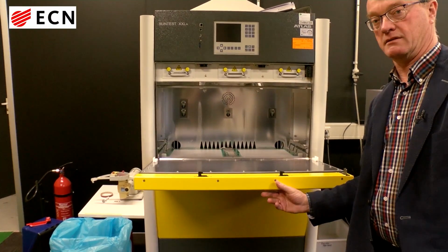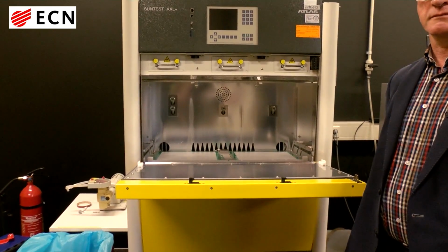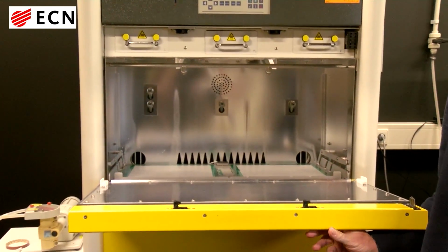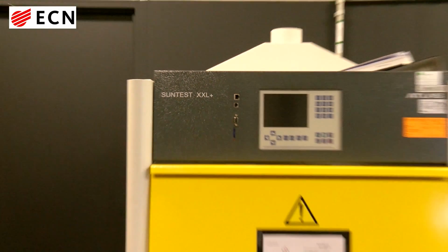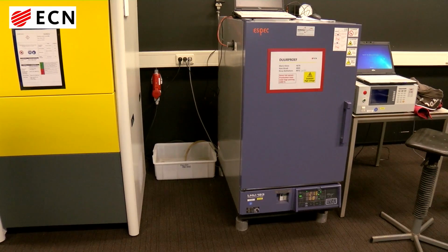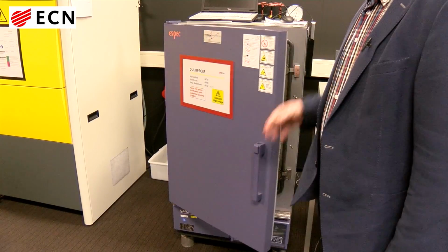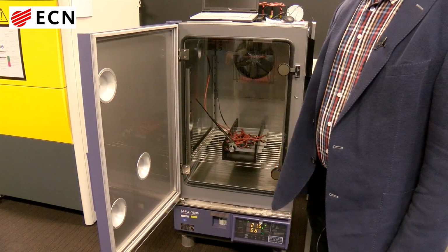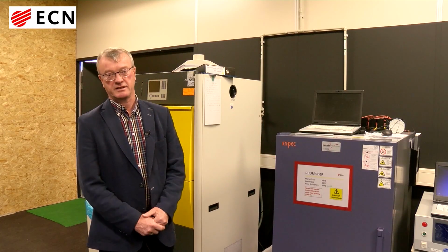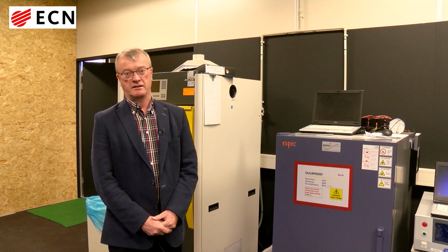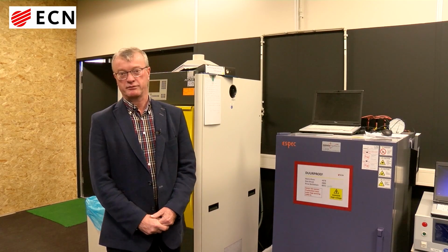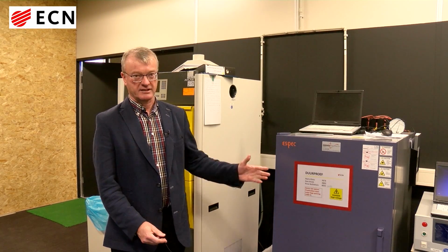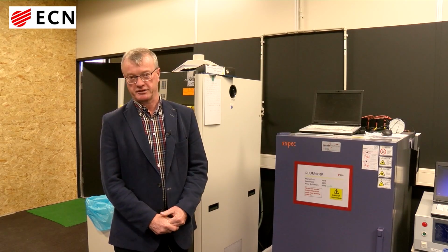This is an example of a UV testing chamber. The lights are not on since this is harmful for the eyes. The other machine is a climate chamber where potential induced degradation of modules is tested. In this chamber we are testing the degradation induced by a high potential in a PV system, especially the large power plants. The voltage can build up to 1000 or even 1500 volts, and here we're testing the durability of the modules with those high voltages compared to the bias voltage, which is around 0.